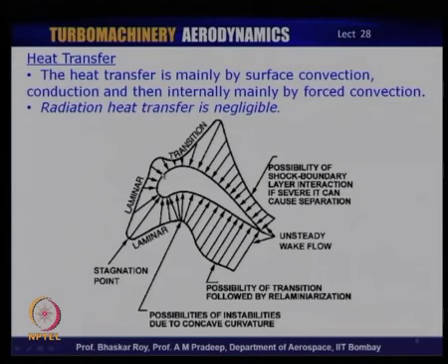Now, as you have done in the last class, as the flow transits from laminar to turbulent flow through the transition, the heat transfer from the hot gas to the body of the blade is facilitated, which means there is more heat transfer across the body of the blade. As a result, the blade would actually be getting more heated towards the rear part of the blade, where the static temperature may be falling off. Here, the blade is probably somewhat shielded by the laminar layers, and as a result the blade feels lower temperature, even though the temperature outside is actually much hotter. So, near the leading edge, temperature outside is much hotter, but the blade feels less, but later on, even if the temperature is falling off, the blade actually is made to feel much higher temperature on the blade surface, because the boundary layer outside is turbulent boundary layer.